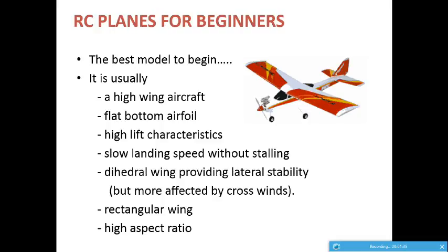So to begin with, you always need to practice with simulators. You can get them in the market on CDs, or you can download them from the net. But you need to have a good knowledge of the radio control, the simulation part of it. Only then should you begin flying a real aircraft model in the environment.